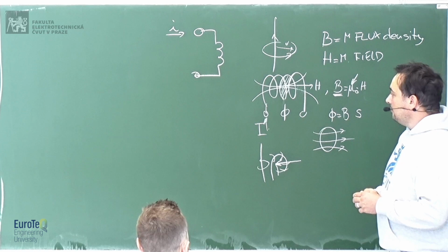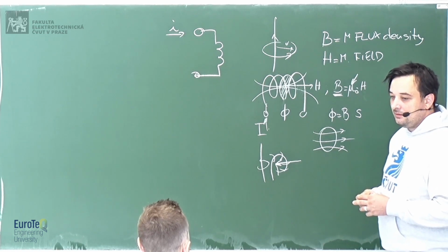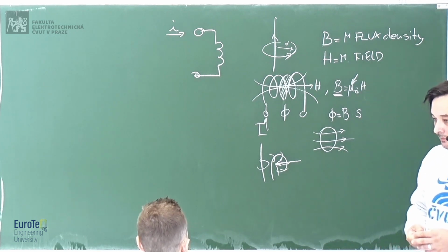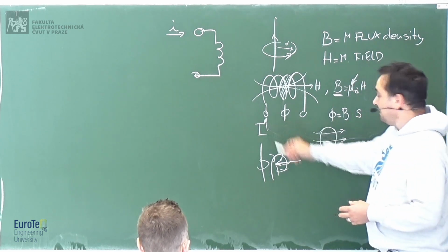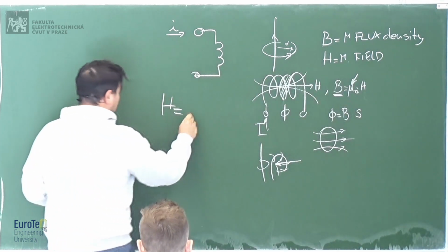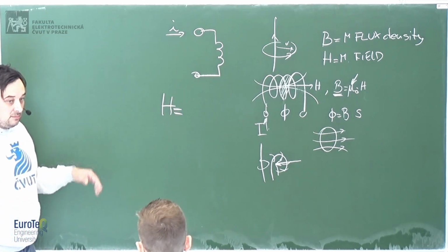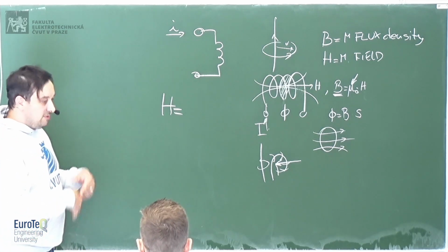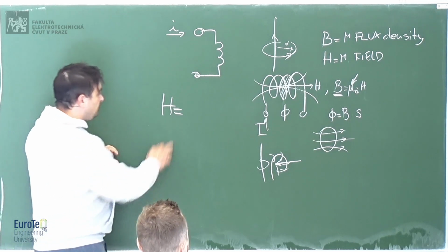How do you think is the relationship between a flux and a current? Proportional, because if you double the current, you double the flux. But there would be a saturating point. Not in air. In air, no. Or if there's an iron core, you could. If you have a ferromagnetic core, then it will arrive to some saturation. But let's keep it with air.